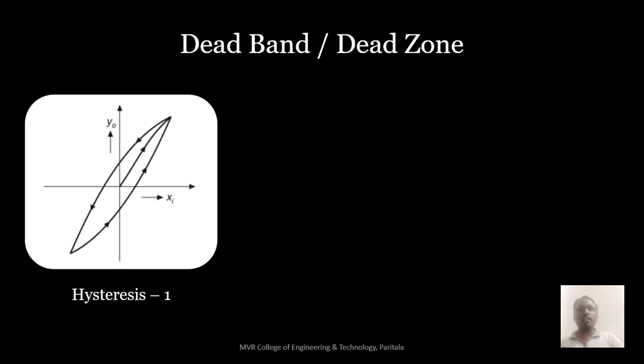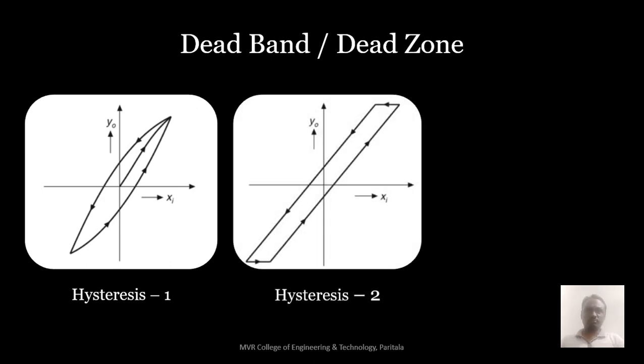Thereafter, if you increase the negative values, again it will go to the full scale value, following a certain curve. This curve, as you already know, is called the BH curve or hysteresis curve. It won't return to the starting point again. So this type of error is called hysteresis error. Practically, after calibration, these types of errors will occur in instruments or measuring systems.